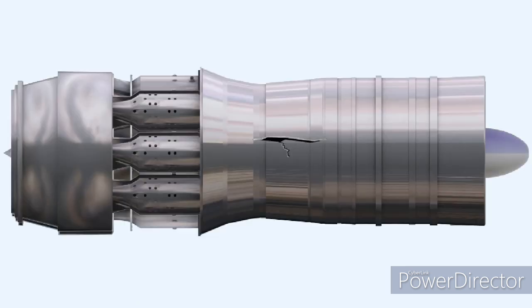The reason for limiting the thrust restoration of the turbojet engine to that of its flat-rated performance is that, although the mass of the airflow could be increased, with relatively few complications, by increasing the compressor speed, the maximum compressor outlet pressure has to be limited to prevent the engine compressor casing splitting under the excessive pressures that would be generated by using such a procedure.